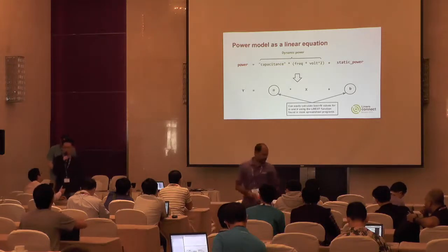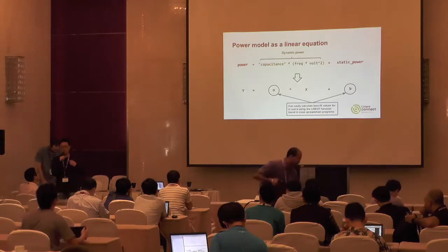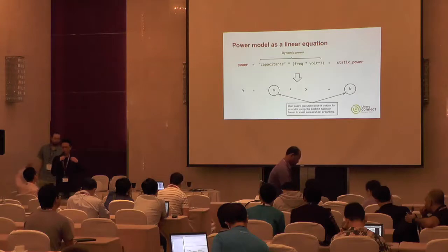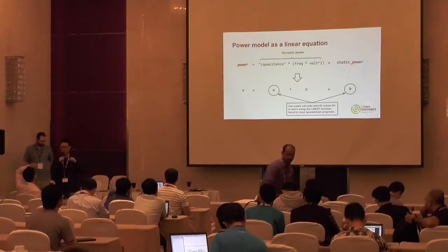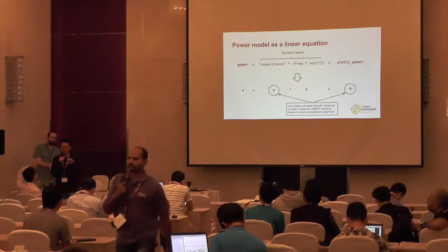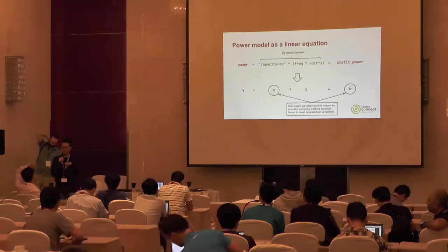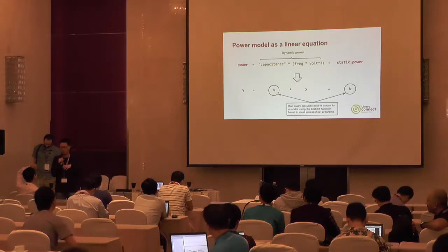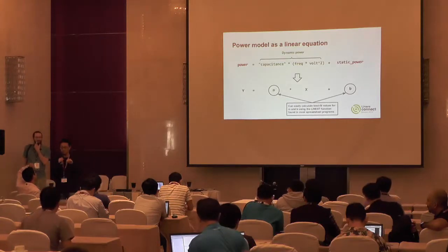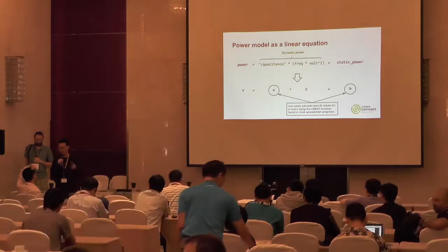The static power we can understand as the clock has been gated for the logic, but the logic still has power, so it will have static power leakage. For example, if the CPU runs WFI, it is clock gated, so it has low dynamic power.